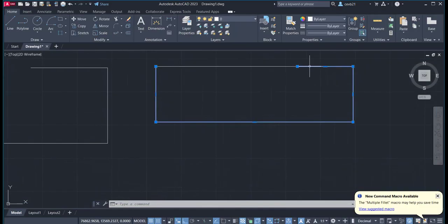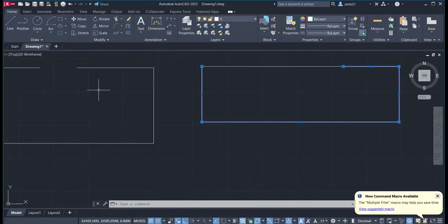So previously, this is a polyline, which is when I select it, all of this is selected. But now, since I used the break at point command, it's already been broken. So this is the difference between break and break at point. Break at point has no gap, while break will have a gap like this. Okay, so these are your modify commands. So next,